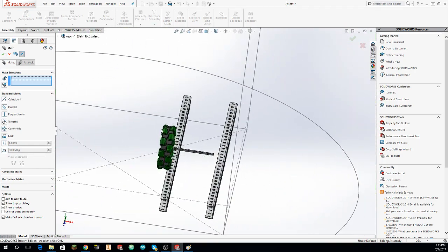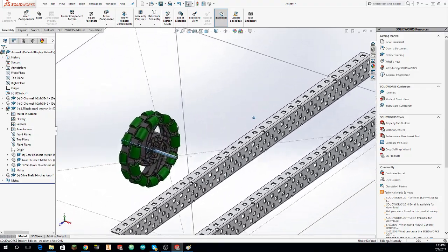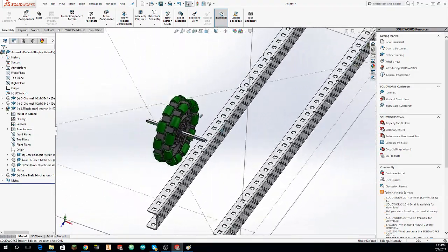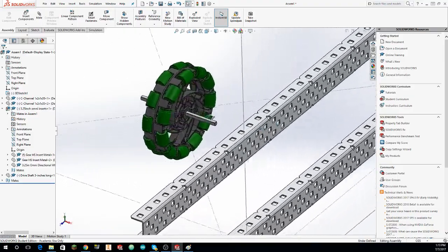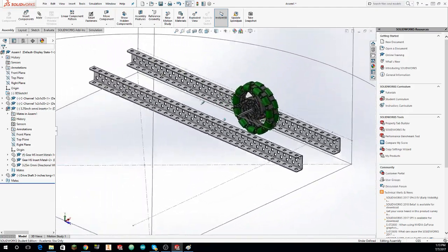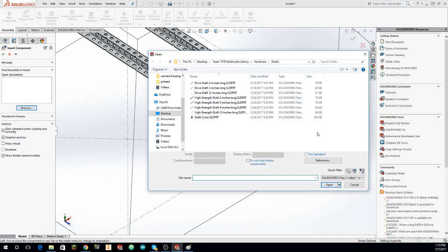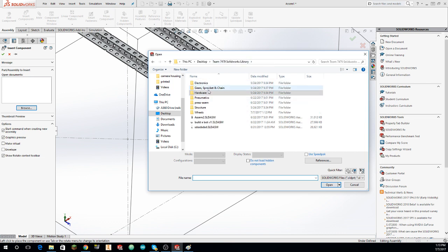There we go. So, I'm thinking that we're going to be definitely doing a 6-motor drive, because there's not really much that we're going to be using for motors. A double reverse 4-bar has a lot of weight to it, so it needs a lot of power to move it up and down to overcome momentum and such. But since we're going to be using just a 4-bar and then a chain bar, it's going to be requiring a lot less power. So I'm thinking we're just going to be using 2 motors on the lift and 2 motors on the chain bar, and then 6 motors on the drive, which should work pretty well.